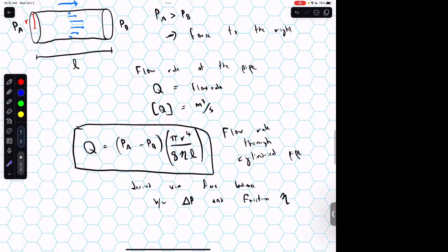Okay, so this is the equation for the flow rate Q in terms of a pressure differential times a bunch of properties of my pipe and my fluid. This is usually something I can control by increasing how much pressure I apply at my front end. But a lot of this is usually external to my problem. I have to pump oil, so I'm stuck with this, and my geometry is set by whatever my manufacturing tolerances are.